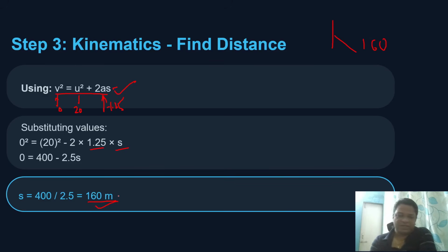So always remember Newton's second law: force is equal to mass into acceleration. And in this question, a combination of friction and dynamics is asked. So from that you can identify that even some dependent motion questions will be there in the final examination. So you have to draw the FBD as well as the kinetic diagram. The kinetic diagram will have the component of mass into acceleration. So as per the direction, show the mass into acceleration. Then apply Newton's second law: summation of Fx is equal to mass into acceleration in the x direction, summation of Fy is equal to mass into acceleration in the y direction, and find the required values.